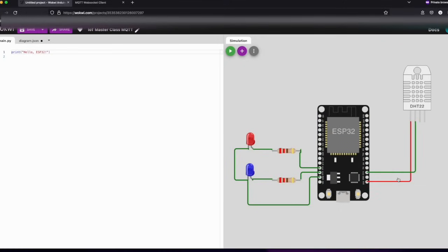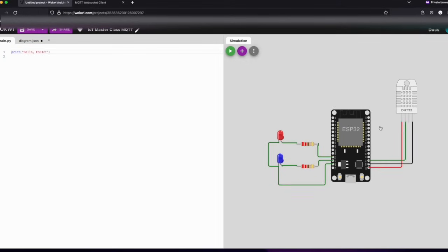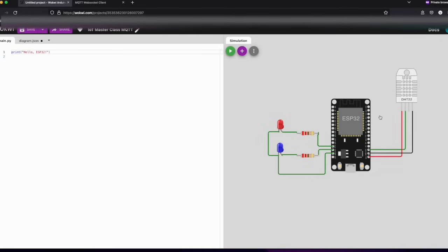All right, so that should go to pin 15, and then the last one, that's the ground. Oh yeah, it was written there. Yeah, that's the SDA, and this is the VCC. I kind of forgot to look at that. So this goes to the ground. So let's just make sure this is VCC, this is SDA1, and that is ground. Okay, it's all labeled in here. So looks cool. What do you think?